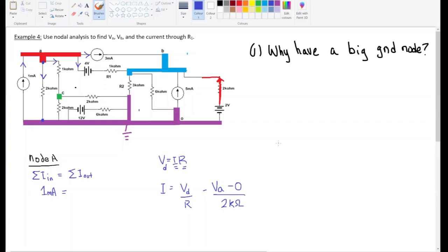It's the voltage drop, like if you imagine you have a situation like this. If the voltage at this point A is 10 volts and the voltage here is 0, then you know that 10 volts dropped across that resistor. If you had a situation where you had 10 volts and you had 5 volts here, well, you know that 5 volts must have dropped, right?